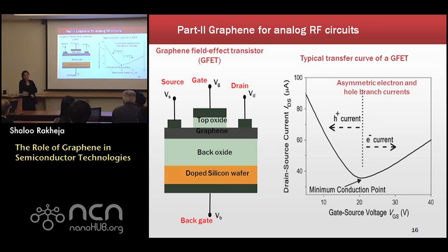Well, for interconnect applications, unfortunately, you have to pattern graphene into nanoribbons. So that unintentionally opens up the band gap. And people have argued that zigzag versus armchair, one of them would be metallic and the other would be semiconducting. And I beg to differ because none of the experiments have shown metallic characteristics. So that is also one of the limitations. While for transistor applications, you want a band gap, for interconnect applications, you don't want a band gap. So, yeah. It's sort of limiting.